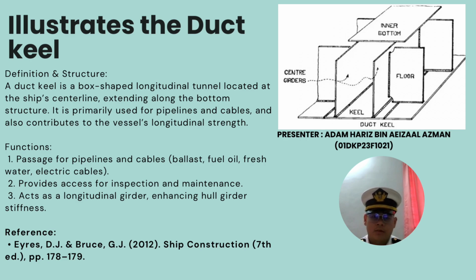Basically, a duct keel is a box-shaped longitudinal tunnel located at the ship's centerline, extending along the bottom structure. It is primarily used for pipelines and cables, and also contributes to the vessel's longitudinal strength. For the function, first, passage for pipelines and cables: ballast line, fuel oil, freshwater, and electric cables. It provides a safe and protected route away from the cargo hold or ballast tank.